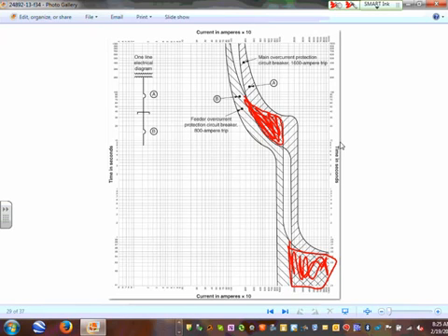So what do you do when you have circuit breakers like this? You move their curves away so they don't overlap. If you have a short circuit within this range, you're guaranteed only the right circuit breaker will trip, not both of them. That's what coordination is, guys. You adjust these circuit breakers so they can play peacefully with each other, meaning the one closer to the fault will trip first.